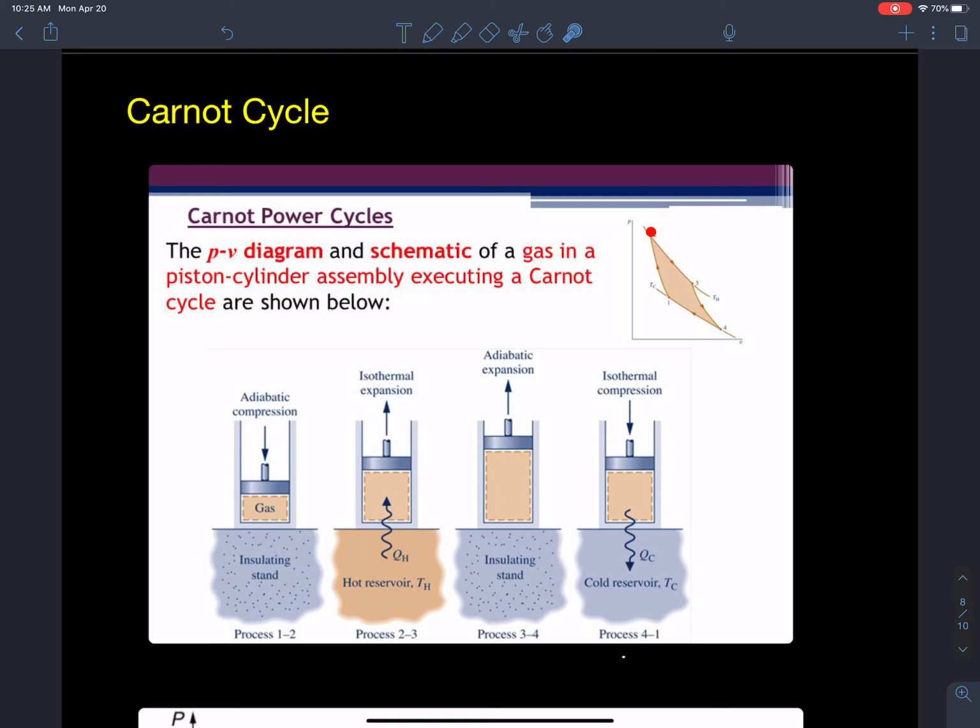Okay, and then at that point, from that higher temperature, heat is going to be funneled in from a hot reservoir. Now that's more likely like fuel igniting inside of the piston, adding heat, and that would cause an isothermal expansion. So that's a lot of area under the graph over there, a lot higher area than if it went from over here. So we got a lot of area under that graph to do work. And then as it's in the upstroke, because of that explosion, it's rapidly moving that piston up. That piston and the flywheel are going to have inertia, and it's going to keep on expanding even though we're not putting heat in there, which causes an adiabatic expansion.